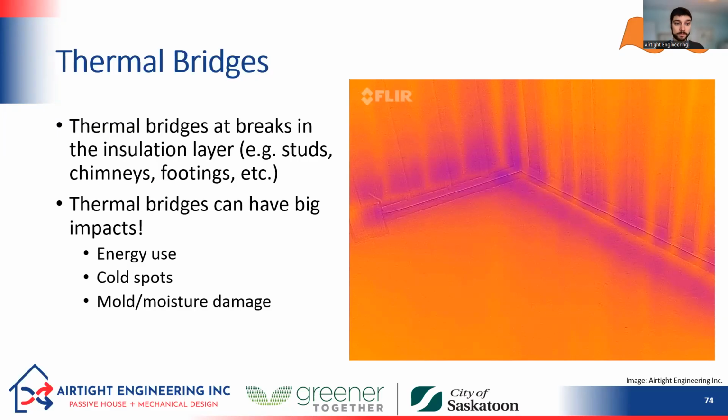So this could be a concrete footing. This could be a chimney, a brick or stone chimney poking up through the insulation, conducting heat. Could be the studs in a wall. And they can have really big impacts. They impact our energy use. They can also create cold spots, which lead to moisture damage, potential for mold growth, etc.